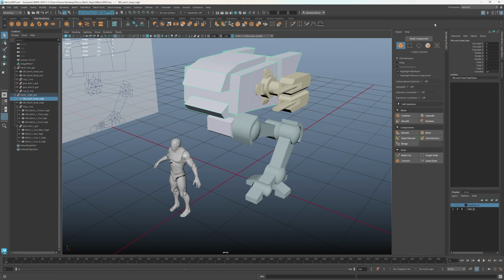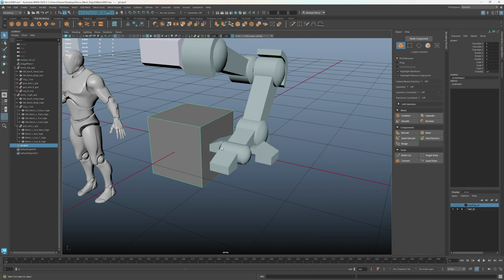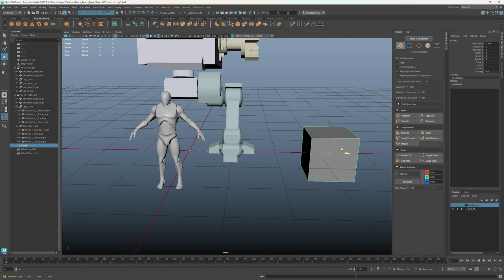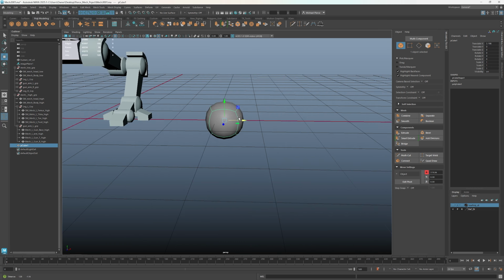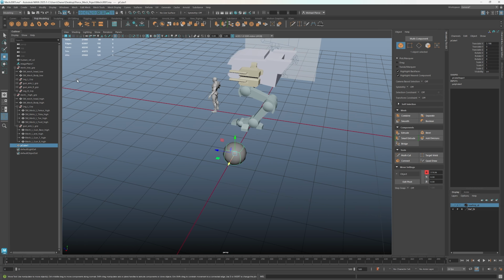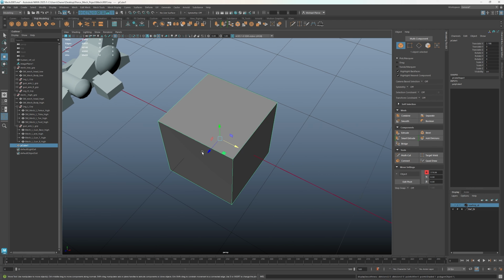So now I need to go around adding control edges to my things so that we can subdivide this up. Now, as a good example, I'm going to give you a quick example, right? Subdivision is like when I hit 3 here, we have the smooth mesh preview. You see how this cube just literally crushes, like basically shrinks in on itself, right? So when you smooth it, it interpolates where it would be based off of it, trying to figure out with the calculations to bring everything in, right?